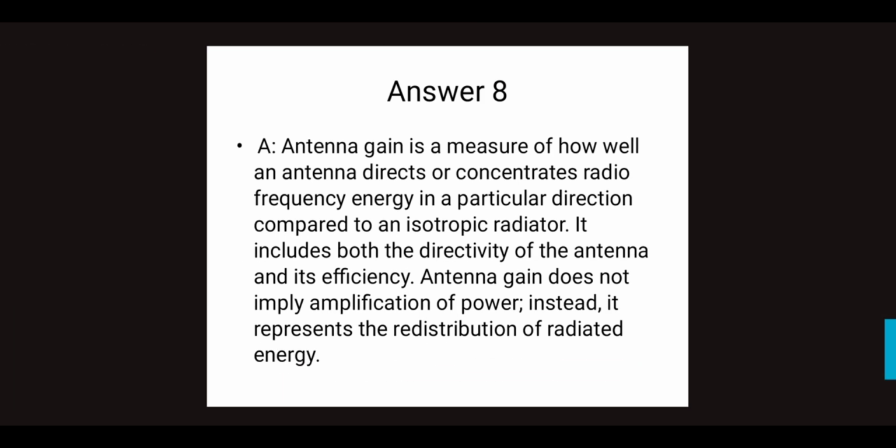So it says antenna gain is a measure of how well an antenna directs or concentrates radio frequency energy in a particular direction compared to an isotropic radiator. It includes both the directivity of the antenna and its efficiency. Antenna gain doesn't imply amplification of power. Instead, it represents the redistribution of radiated energy. So that is what we have just discussed.